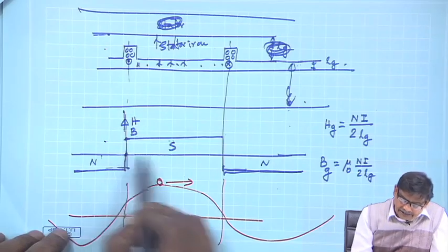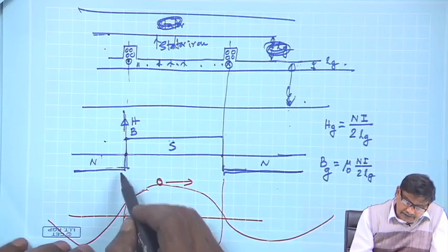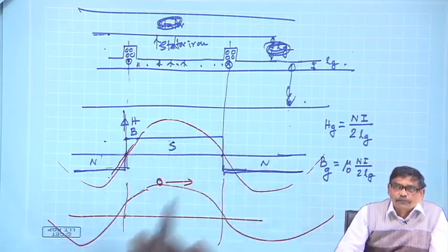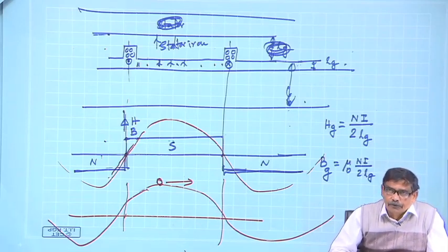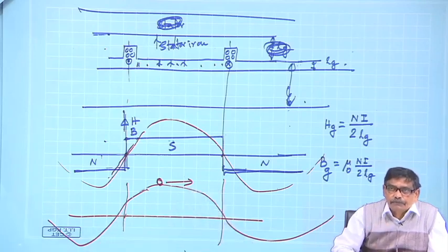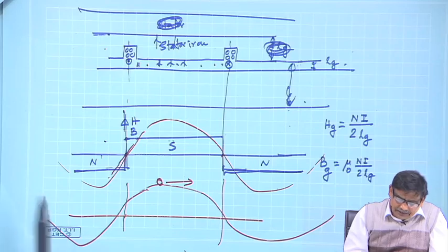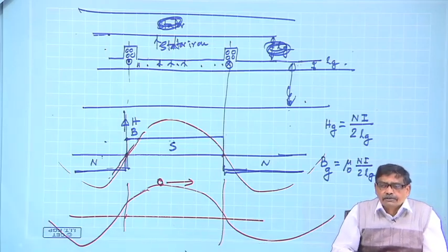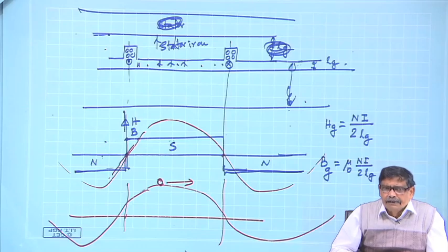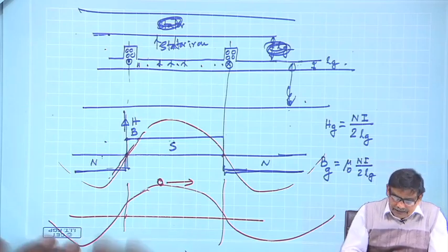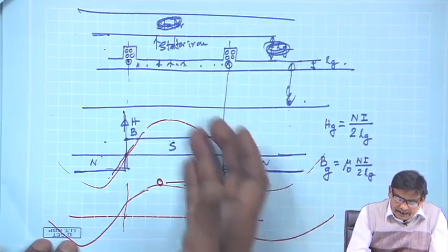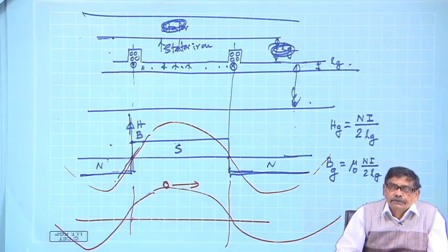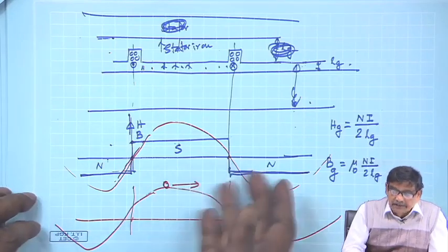For example, for this waveform, you know Fourier series, I can Fourier analyze this and get a fundamental sinusoidal with a lot of harmonics. One good thing is that higher order harmonics will have reduced amplitude. So, you can say that it is a square wave, but it has a strong fundamental sine wave with a lot of odd harmonics. And the idea is whether this B can be made a very nice smooth sine wave like this. What can be done is that we will try to get an approximation to this sine wave, and that I will discuss in the next class. Thank you.